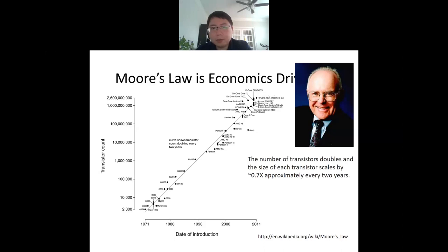But we see that Moore's law is going to slow down. Actually, it has already slowed down in the past few years. So from generation to generation, nowadays it's not 2 years, maybe 3 years, and in the future maybe 4 years, because we are reaching the limit of the physics. As of today, the transistor gate length, as we showed before, is like 10 nanometers, and the silicon atom, we talked about that before, the atom size is about 0.3 or 0.4 nanometer. So from the source to drain, you only have about 20 atoms.